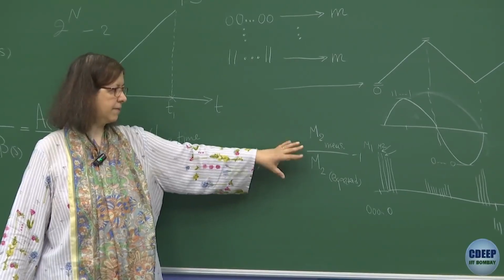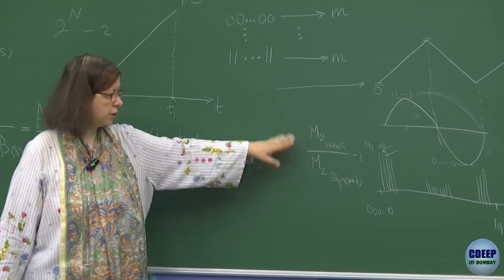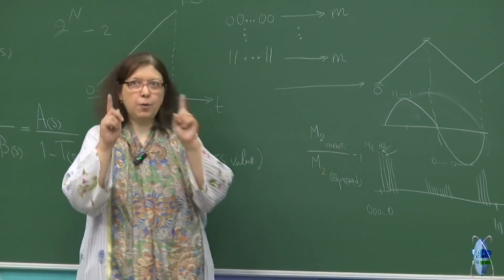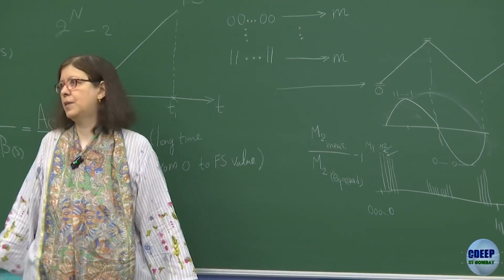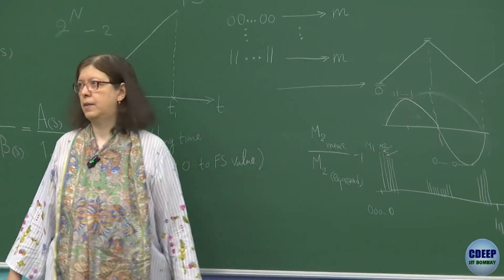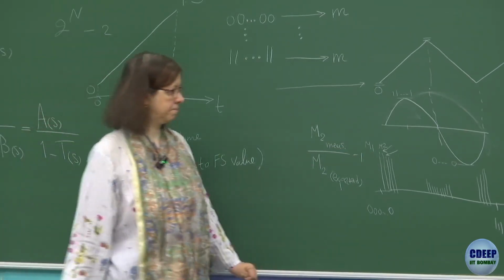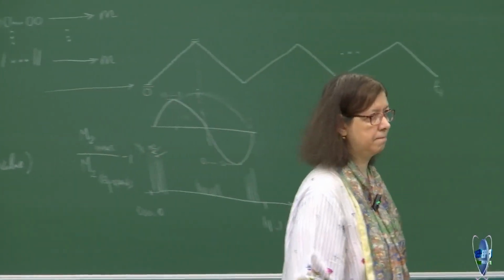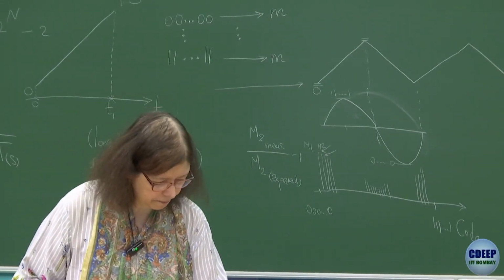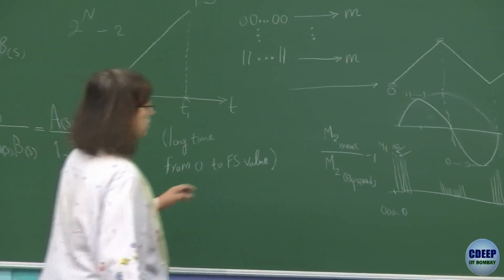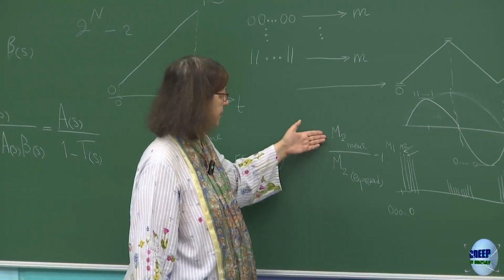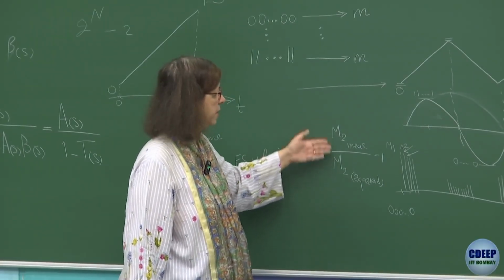Otherwise, it is exactly proportional to the reduction or increase in the number of samples for M2, equally the segment size has increased or reduced. That's why it is still applicable. The only point is that it's not the same for all codes. So the expression is applicable, but the actual numbers are not. The ideal value changes for the expression, because it is ratios. For DNL, it will be the same, and INL anyway is derived from DNL. So actually, it's correct.